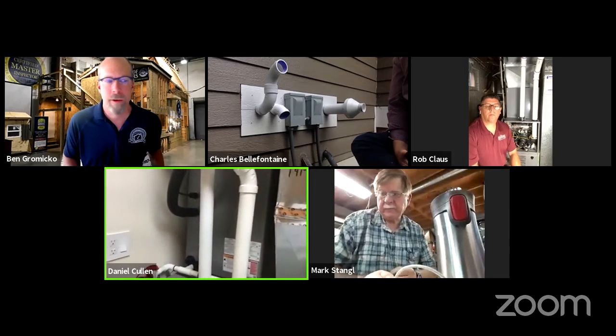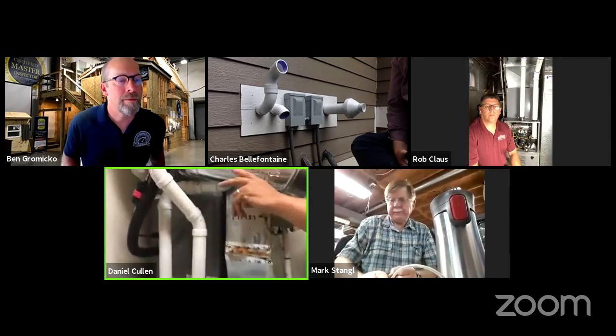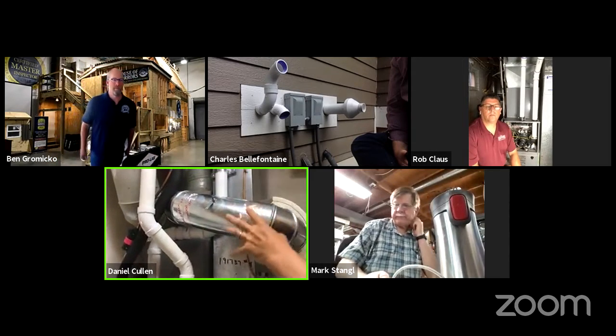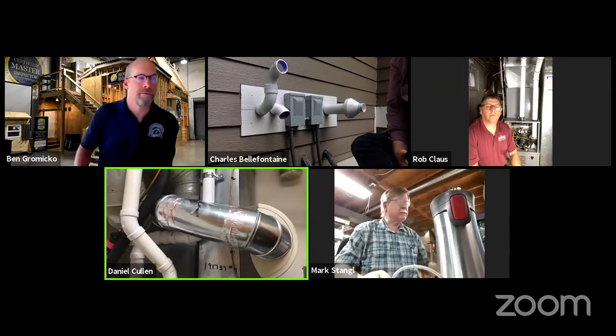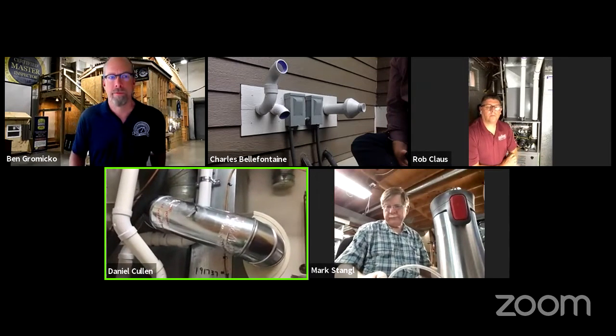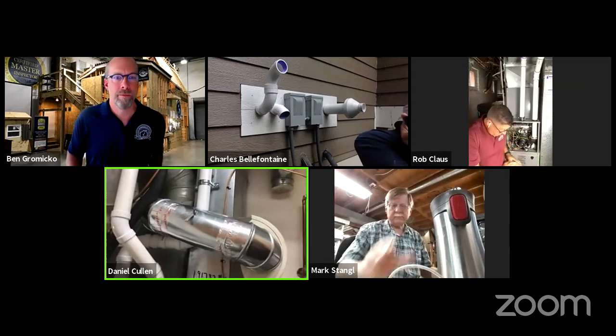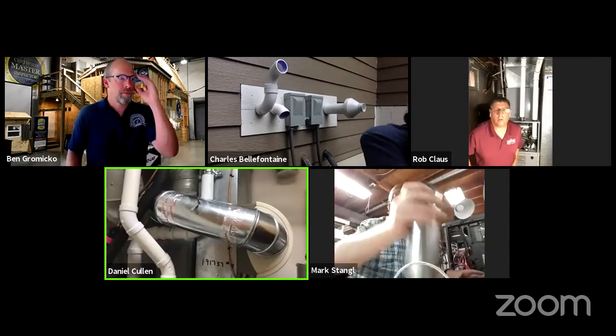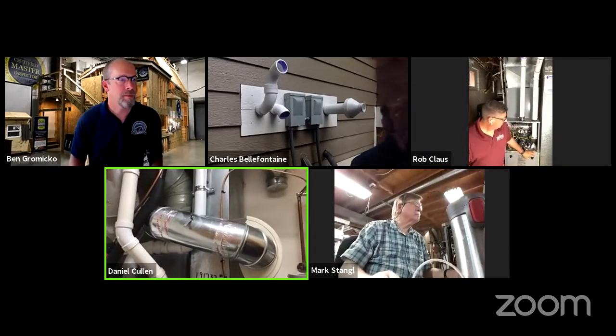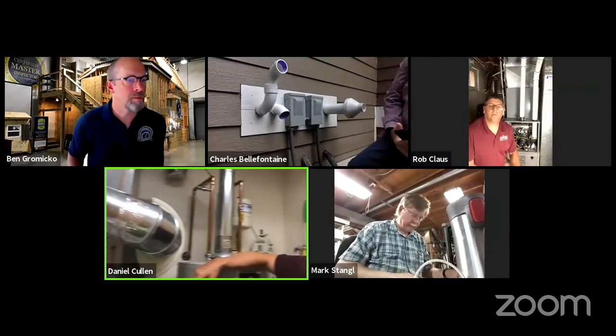Another thing that really shouldn't be in this house, but we have it, and maybe I'll eventually change it, is a bypass humidifier. So in our temperature, like you guys in Colorado, it does get dry in the wintertime. And it's not only more comfortable to have humidity in the air, it's also healthier, as they've found out recently with the COVID virus. When there's adequate humidity in the air, it gives viruses, bacteria, and mold spores something to plate onto and fall out from the air. When air is super dry, those type of little tiny, very fine particles stay suspended longer. So humidity is important for a couple of reasons.